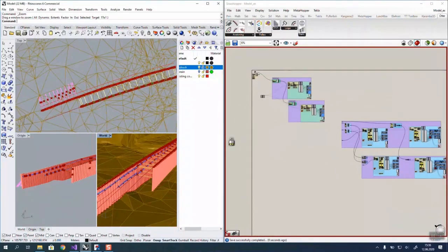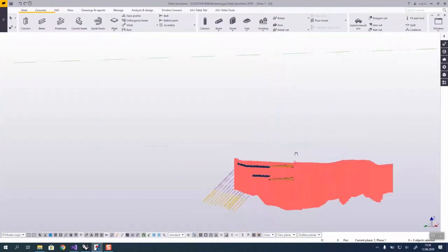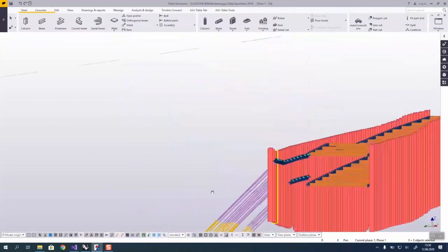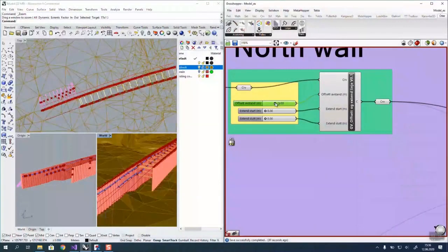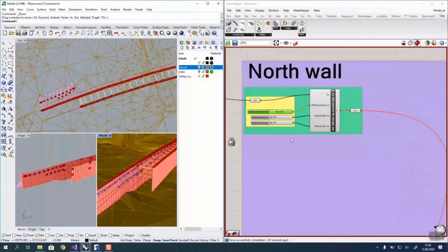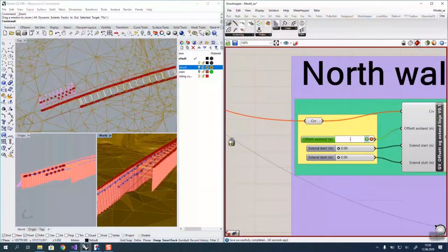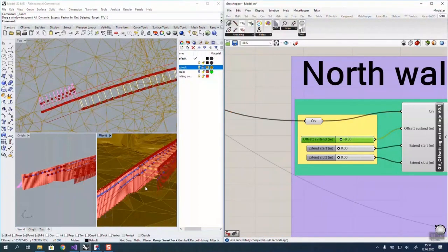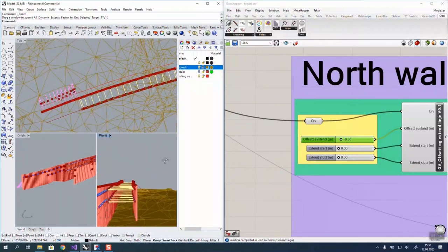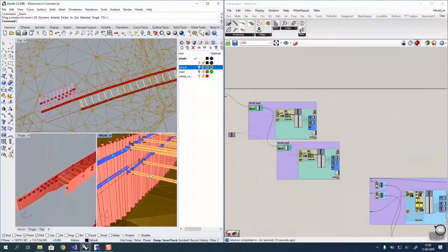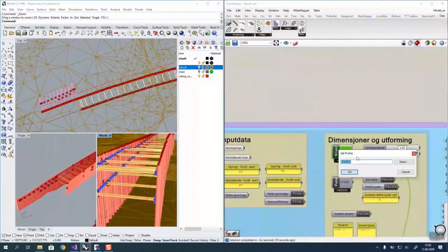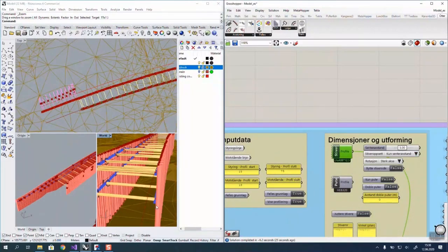I would like to send this to the structural engineer for some comments and so on. And now I already got a message from the structural engineer, as he says he wants to change something in the model. So they need additional distance from the construction to fit the formwork. So we need to give them 1 meter extra space for that. And of course, that's an easy adjustable to do in Grasshopper, as you can see. And as you can see, when we move the northern wall, we also define to move the southern wall, and automatically all struts and anchors follow.